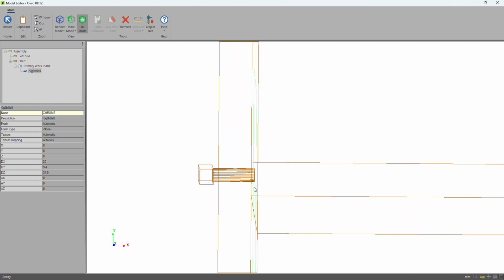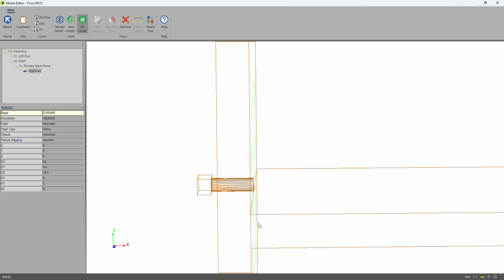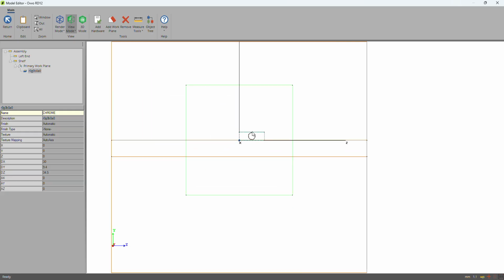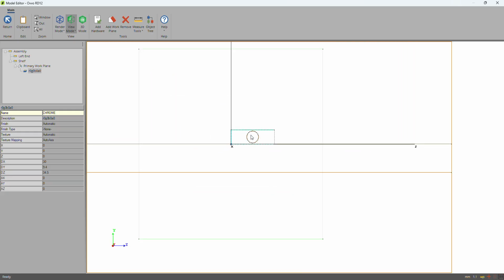Now we need to bring this model in so that it sits correctly between the parts. So we go back to left again. The equations we need to do are very simple, because I need this whole thing to always sit in the middle here and in the middle there. So we can modify it with equations. If you select the part on the left, you can change the name under description. I'm just going to write model there, so that it shows up correctly on the drop down.